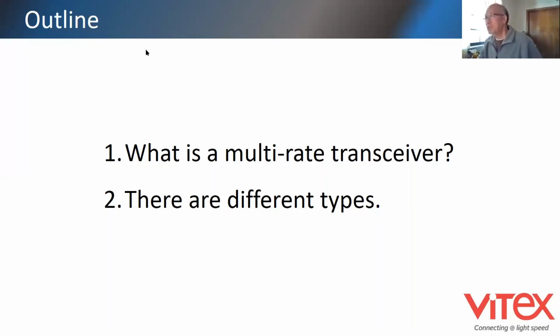So do you suggest using a multi-rate transceiver compared to single rate if the cost is not a constraint? Yeah, so one thing my presentation emphasized is the performance difference. If you try to meet a certain MSA, you must make sure the multi-rate transceiver can support it. Sometimes they cannot. You need to make sure that those specs are specified in the data sheet. If they aren't, it might not be a compliant transceiver. Yeah, so it's all specsmanship. You need to be very careful when you select a multi-rate transceiver.